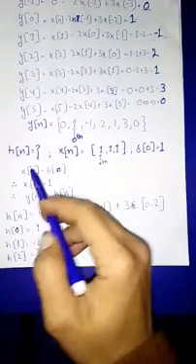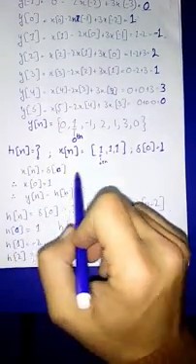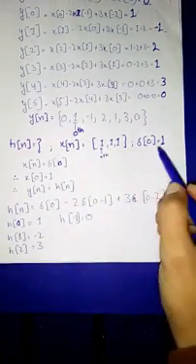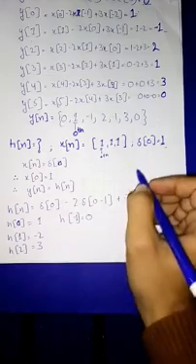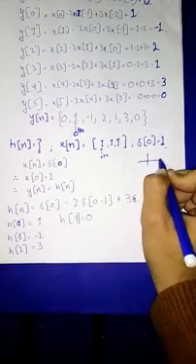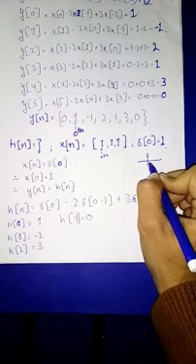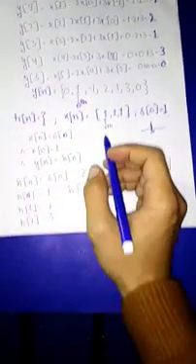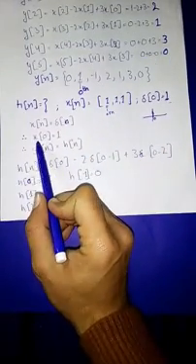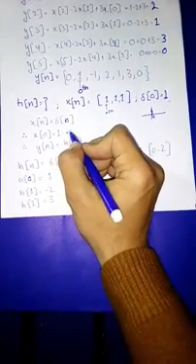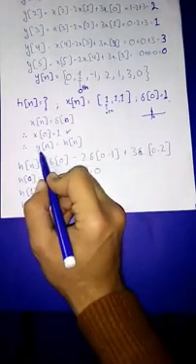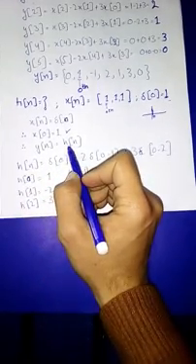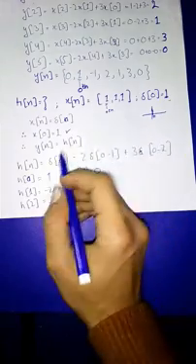Okay, now when we see the impulse response of this particular system, we will have to replace x of n with the unit impulse, and we know that the unit impulse is 1 on the 0th position in the time axis. Here we have a 1 at 0, so x of 0 will be equal to 1. This is the only definition of our system. The y of n will be replaced by the impulse response of the system.